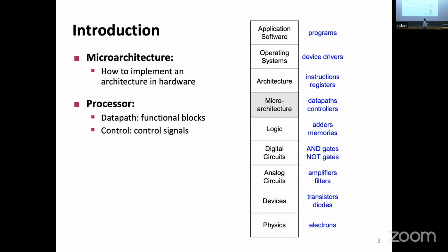And the architecture was already taking into account some physical realization issues, because the RISC processors are made in a way so that they can be implemented more efficiently in hardware. So we made some compromises. We said, we don't want to have all kinds of instructions. We want to have a minimal set that can be very flexible, can do a number of things. But we want to make sure that these things that it does, it can do very well.